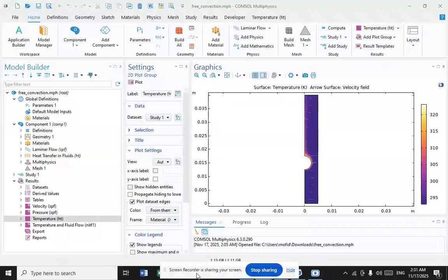It is also shown that the cross-correlation coefficient for shear stress becomes zero near the wall, which is in contradiction to analytical analysis. Turbulent natural convection around a heated vertical slender cylinder was studied by Persson and Karlsson in 1996, and new turbulent structures were presented for the near wall region. Again, it was shown that there exists a negative shear stress region close to the wall, comparing normal stresses and temperature fluctuations with those proposed by Nagano in 1988.